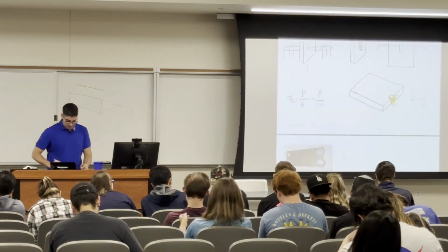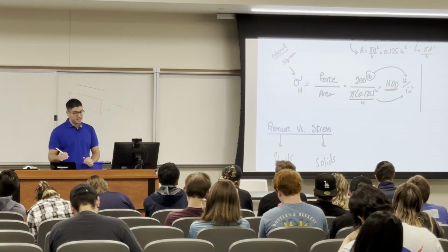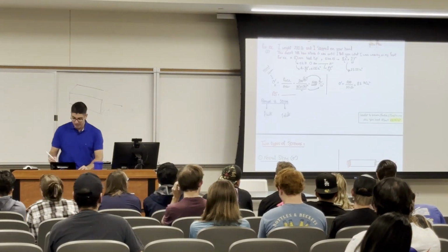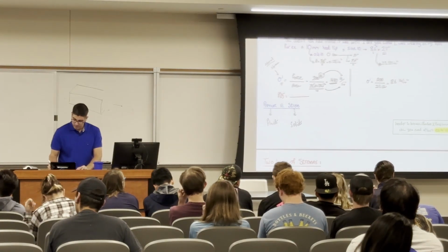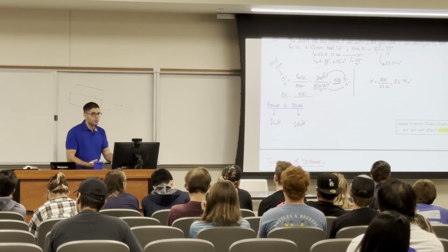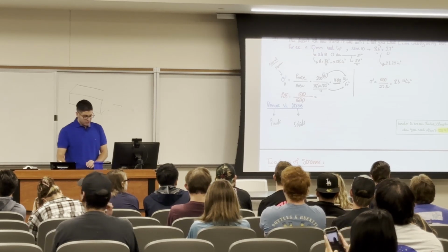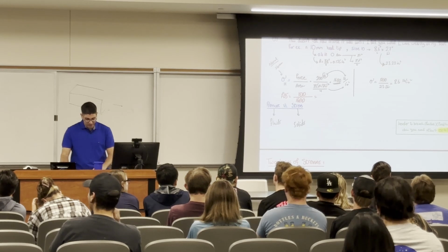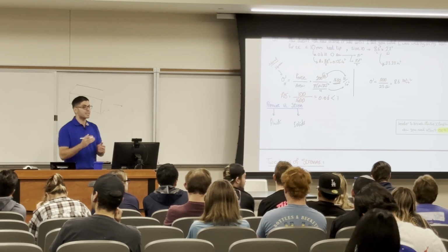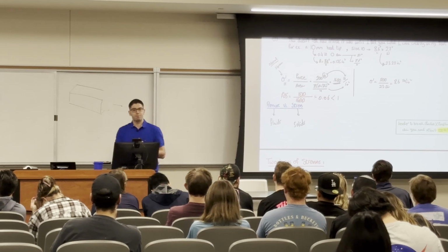Let's go back to this problem that we had here at the beginning. We applied a stress of 1600. The capacity of the skin was 100, right? So if I say 100, that's the capacity. The demand is what stress I'm putting on the skin, which is 1600. Right? So is this going to be greater than or equal to 1, or even less? It is 0.06, which is less than 1. That's why the skin is going to fail. So if the factor of safety is less than 1, then it's going to fail.